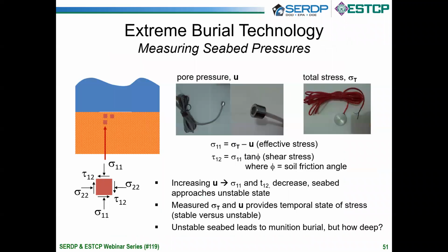So let's talk about our surrogates here. This is work that's come out of collaborating with Scott Wassman and Ed Braithwaite and Chuck Key, our engineers, with help from Carter Duvall, who have all been working together on this. What we're trying to measure are the pressures inside of the seabed. So we're using combinations of what's called a pore pressure sensor and a total stress sensor. You see I actually have a little bit of math on this slide. But the important point is that we are trying to provide time domain observations of the phenomenology.